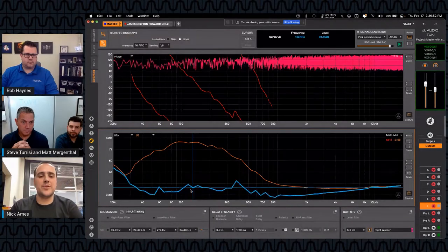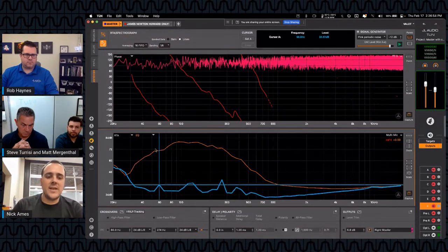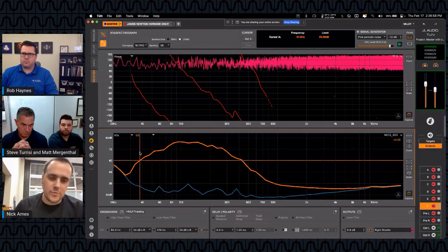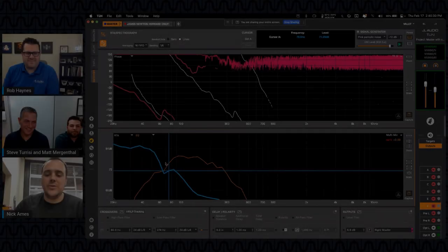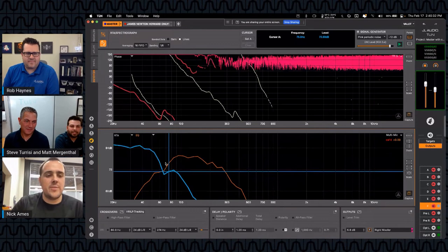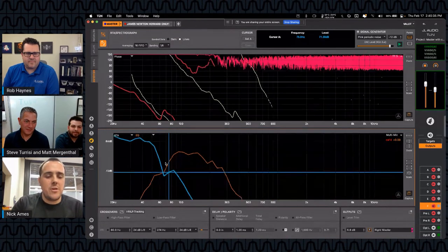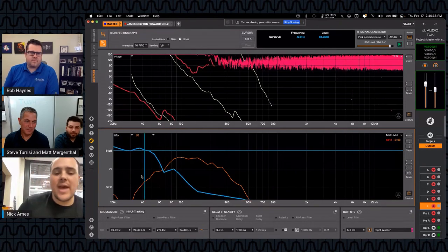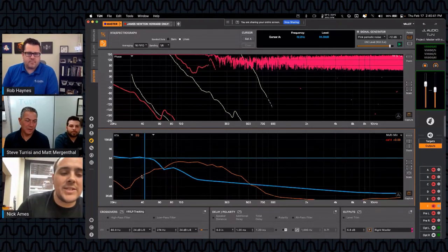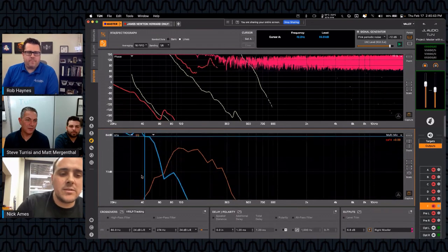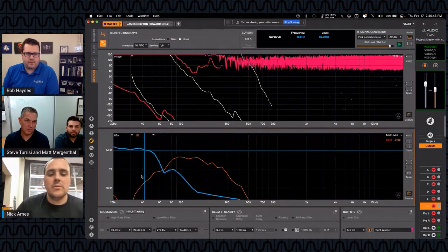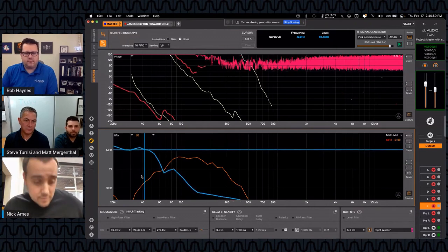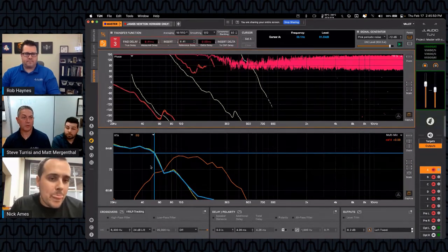So I just have the summed response. I have the summed phase and the orange down here on bottom. That's the summed RTA response of the mid-bass speakers. You can use your plus and minus buttons on your keyboard and it'll scale the y-axis. Y is the up, down, the vertical, right? It'll scale that in or out. So that's the minus key and this is the plus key. And that's scaling the capture data as well. Yeah, anything that's plotted on that graph is going to get scaled with it. The level doesn't affect the phase response.